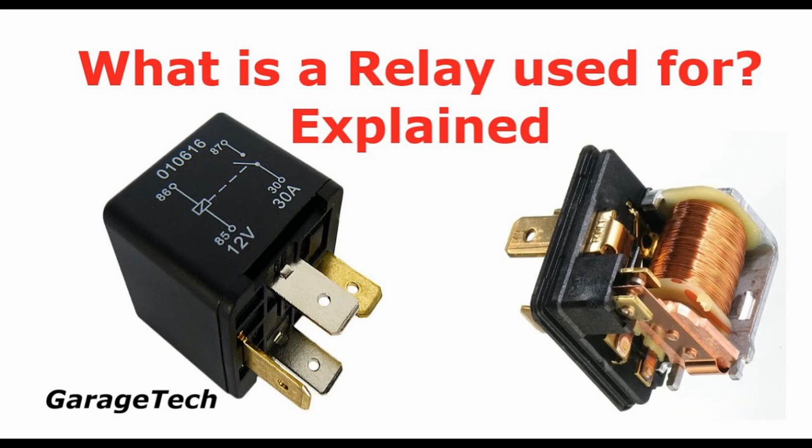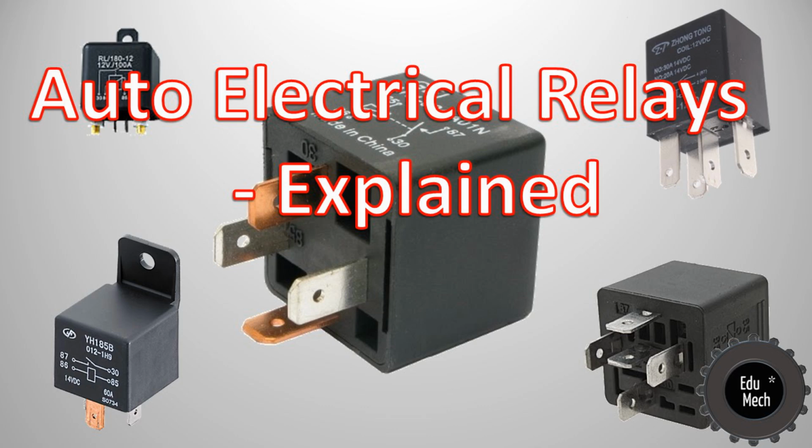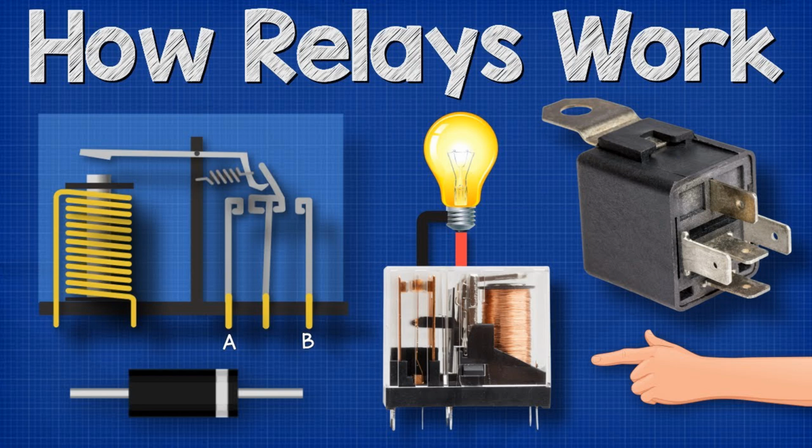making this relay ideal for polarity-sensitive applications. Key characteristics: polarity-sensitive operation. Responds only when the control current is in the correct polarity, providing selective switching. Quick response time. Polarized relays generally switch quickly due to the combined magnetic forces from the coil and permanent magnet. High sensitivity. Requires relatively low power to operate thanks to the aid of the permanent magnet.